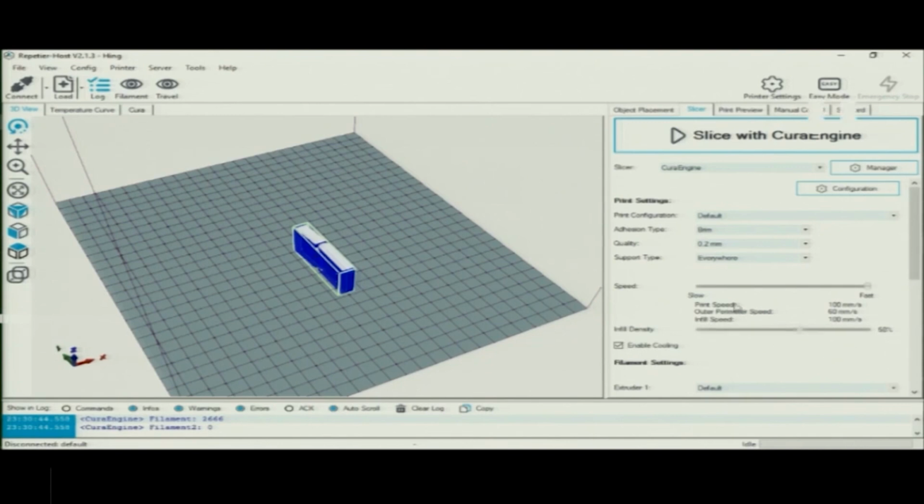It is also the beauty of 3D printing with respect to injection molding. Injection molding is generally used where very high quantity is required, because the dies have to be made and the dies are a little expensive. 3D printing can be hollow from inside. In injection molding, it is very difficult to produce hollow parts from inside. Here we can just select the infill density and we can opt to choose a hollow or a completely filled component. So this was a small demonstration on 3D printing.